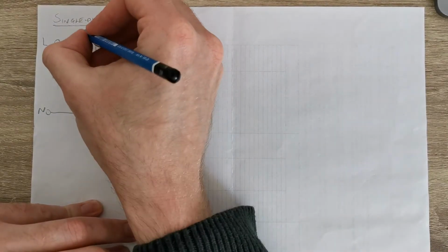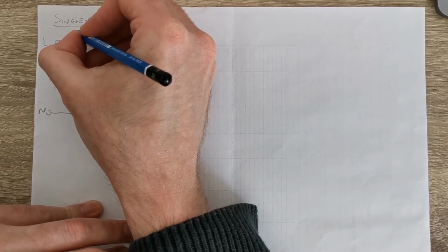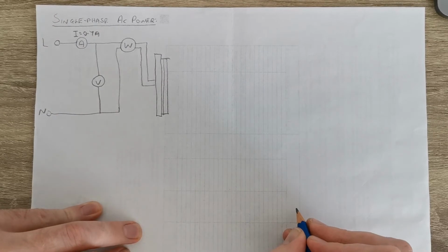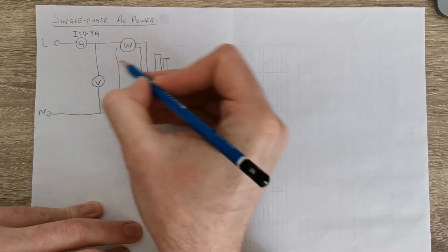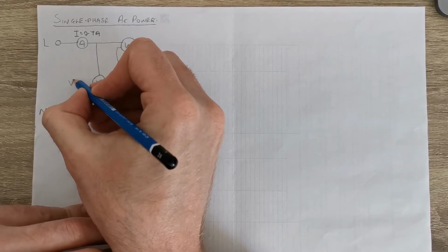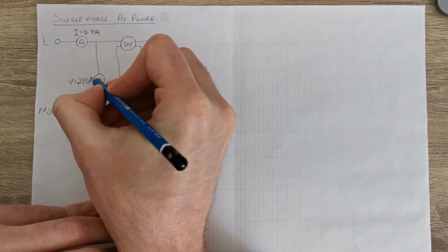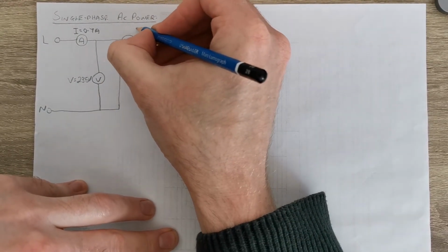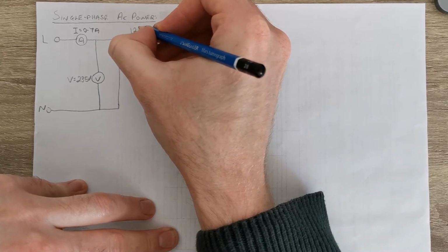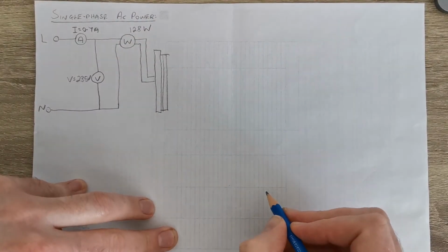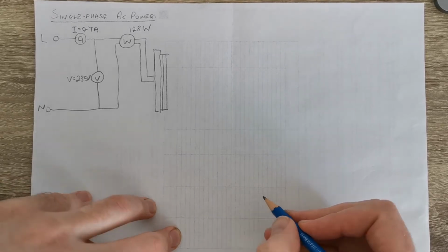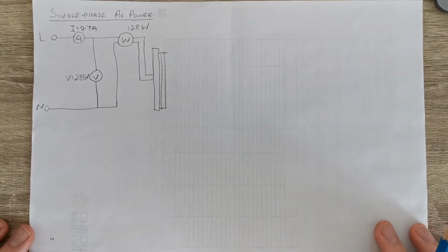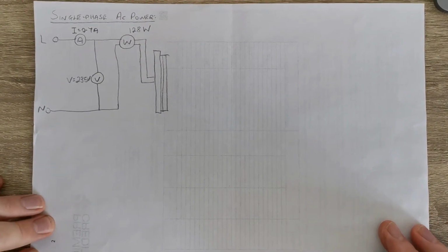So the ammeter is telling us that the current flowing in this circuit at the moment, I, is equal to 0.7 amps, and the voltage coming across the supply is 235 volts. And the wattmeter is telling us we have a reading of 128 watts. And the question is asking us, using the readings on each of these devices, work out the power factor of this circuit. So just to refresh our memory on power factor,